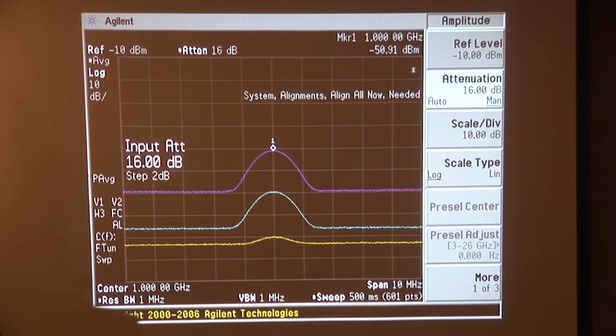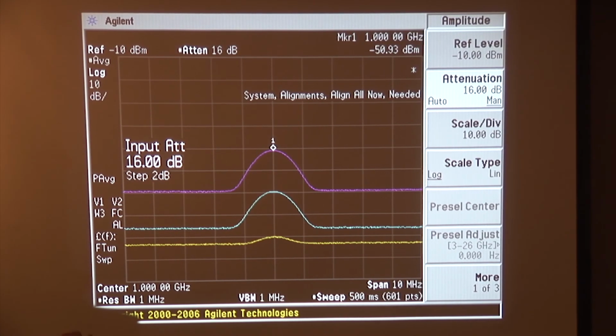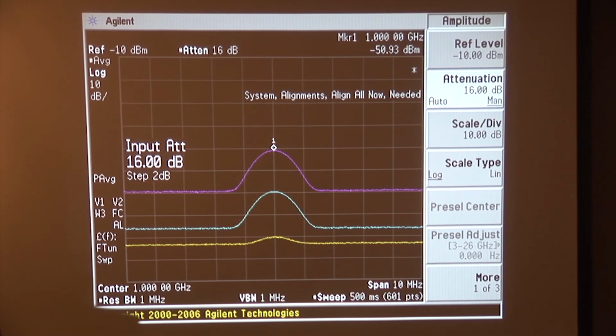Okay, so this is the information that we bring to bear when we're designing any kind of radio receiver, any kind of measurement system. If we're using a spectrum analyzer, the bottom line is if we're trying to get amplification at the front end, we use the cascade gain equation, or you can do it empirically this way if you're trapped on a desert island.